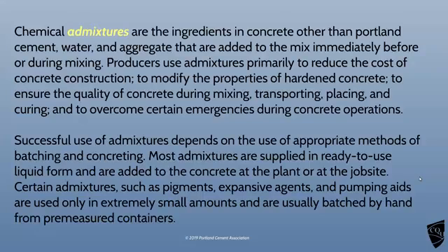To be successful adding these things in there, you've got to make sure you've got the appropriate methods of batching and concreting, so you're mixing them precisely in the right amounts for the design you've come up with. Most of them are supplied in ready-to-use liquid form, so you give it a squirt in there, but you should measure it really. And you can put pigments in to give a nice colour finish if you want to. Things to make pumping aids, to make it stay a bit runny a little bit longer, so you can pump it over.